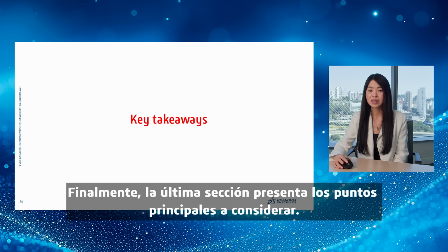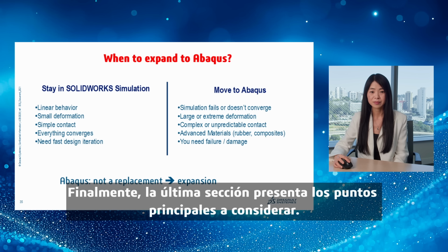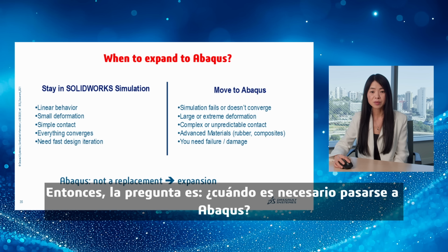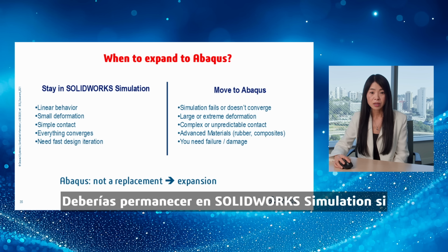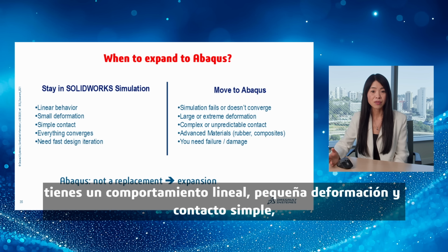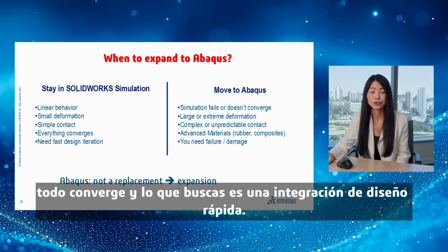Finally, the last section is the key takeaways. So the question is, when do you need to move to Abaqus? You want to stay in SolidWorks Simulation if you have linear behavior, small deformation, simple contact, everything converges. You want to do fast design iteration.